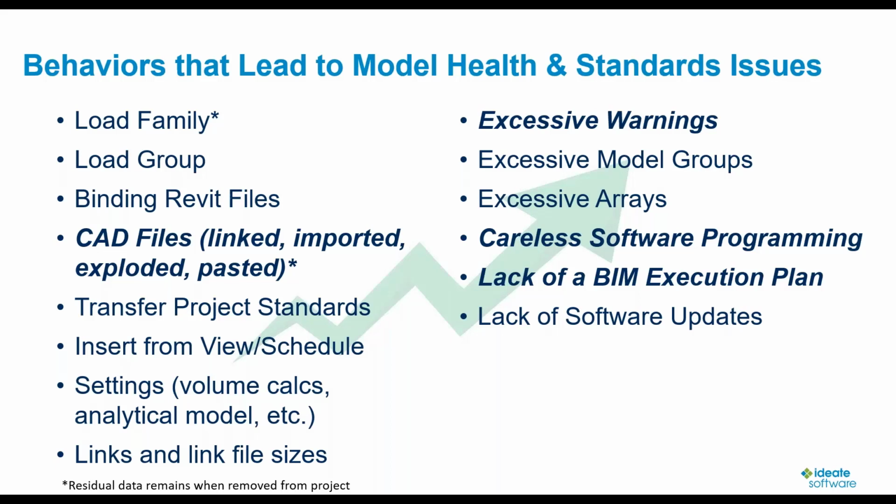There are a lot of checks and balances that you absolutely have to manage, and if you don't, you can end up causing a lot of problems in your Revit projects. And it's never fun if you download an application and then remove it, and then you go to do something in your model and it says this application needs to be installed in order for you to do this. That's because that kind of information is left behind in your Revit projects, even if the software no longer exists on your machine.